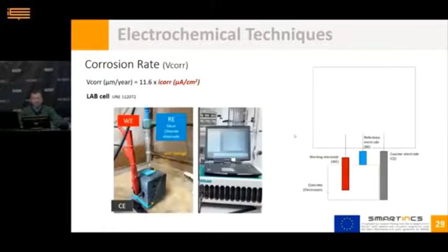To obtain the corrosion current density, the reinforcement must be polarized or disturbed by means of a 3-electrode cell. That is a measuring cell composed of the reinforcement to be evaluated, which acts as the working electrode, a reference electrode like the one used in the corrosion potential measurements, okay? And finally, the third element is a counter electrode, usually a non-polarizable element such as stainless steel or graphite. Concrete is the electrolyte in the electrical measurement circuit.